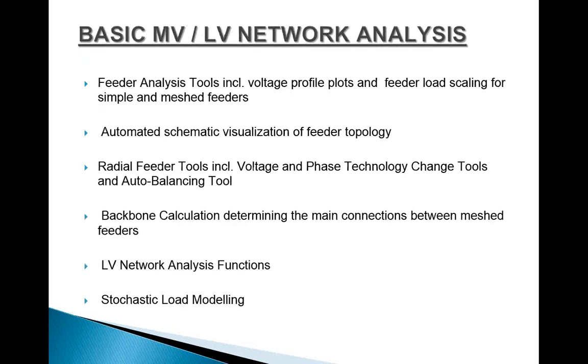Now basic MV and LV network analysis. We have feeder analysis tools, including voltage profile modules and different plots. Feeder load scaling for simple and meshed feeders can be done, and automated systematic visualization of feeder topology can also be done. Radial feeder tools, including voltage phasors, phase technology and auto balancing tools, are present.